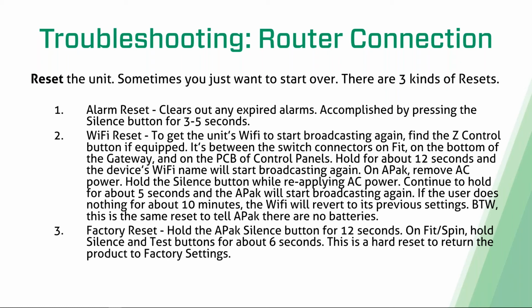All right, and the last reset is basically a hard reset. This is a factory reset. On the APAC, you hold that silence button for 12 seconds. And whenever I say seconds, I mean actual, 1/1000, 2/1000 type seconds. On FIT and SPIN, hold the silence and test buttons together for about 6 seconds, and you'll see everything reset. That just puts everything back to factory settings, and now you know how to help a customer again. You know where you're at. Okay.